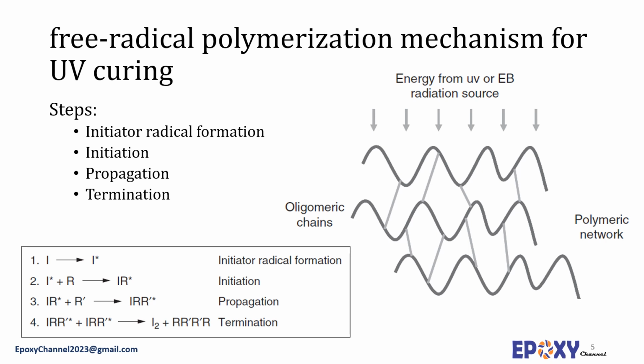reactions. Here, quenching or deactivation of the photoactivated initiator by oxygen can occur, which results in short polymer chains, tacky surfaces, and poor mechanical properties of the coating. However, often the propagation rates are high and oxygen quenching is minimized.